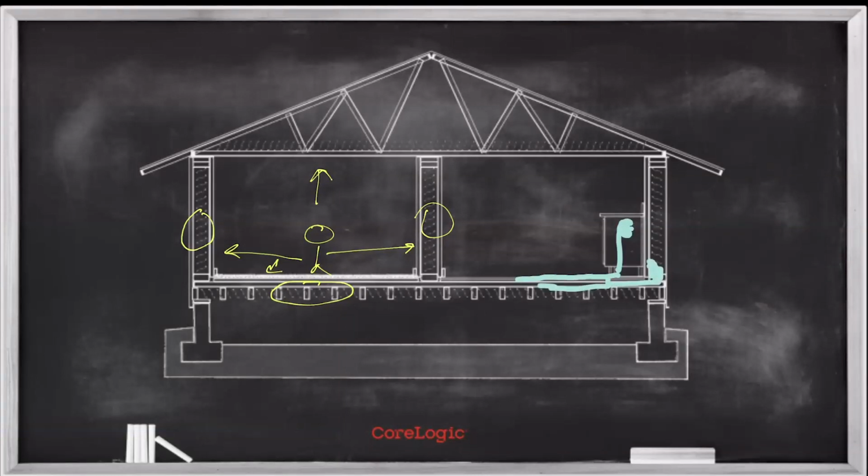And as it absorbs into these spaces, I've got to consider, how have I set up my air movement and my drying environment to ensure that the air movement is capturing the water that is inside of all of these cavities and voids? And again, it comes back to that conversation we had at the very beginning about your instrumentation. The first step in really being able to establish an accurate class and an accurate drying environment or chamber is just making sure that you've actually identified what's wet, right?